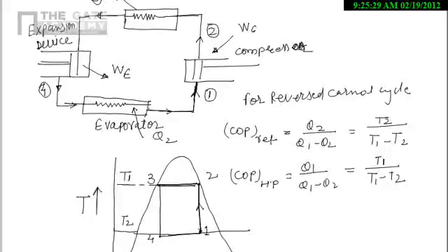to 3 it is a process in the condenser. So from 2 to 3 we will get the saturated liquid at point 3, and we are expanding it in an expander. The use of the expander is that we have to decrease the pressure here. So we are decreasing the pressure from 3 to 4, as well as decreasing the temperature here. So we will get again a mixture of vapor and liquid here, and from 4 to 1 it is